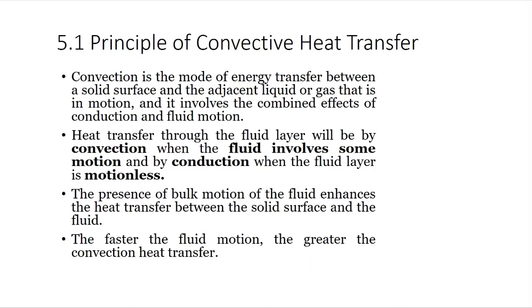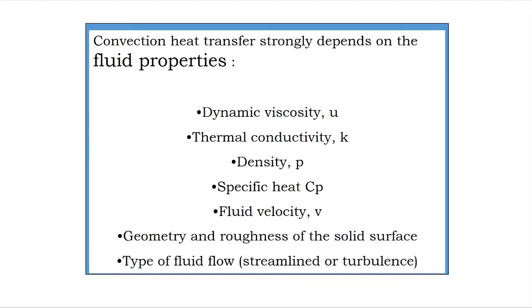Now I'm going to present about the principle of convective heat transfer. Convection is the mode of energy transfer between a solid surface and the adjacent liquid or gas that is in motion, and it involves the combined effects of conduction and fluid motion. Heat transfer through the fluid layer will be by convection when the fluid involves some motion, and by conduction when the fluid layer is motionless. The presence of bulk motion of the fluid enhances the heat transfer between the solid surface and the fluid. The faster the fluid motion, the greater the convection heat transfer.